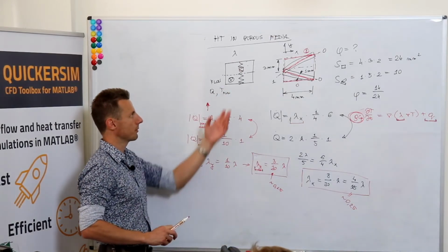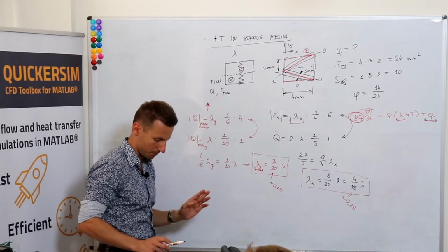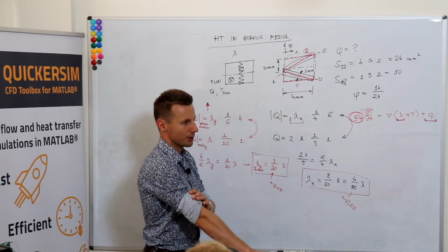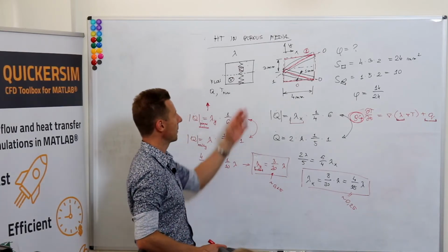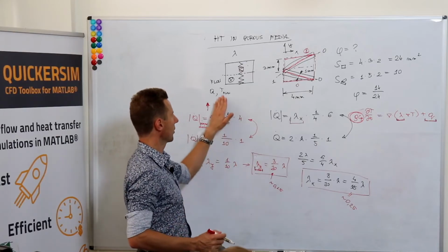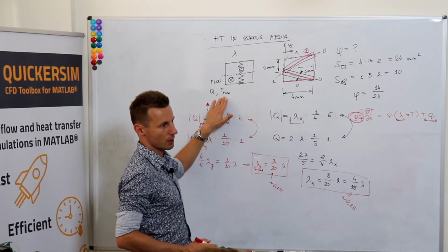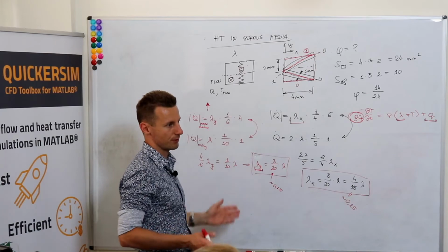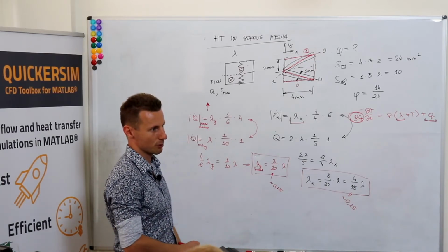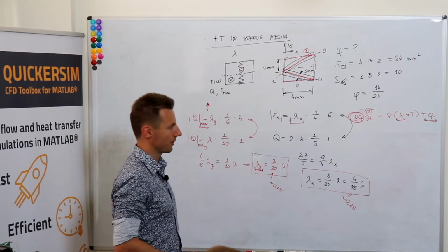If you want to deal with the fluid flow in some different energy balance equation, that's fine. In some cases, you can say maybe this heat exchanger is so short that you simply got flow of air at temperature of 50 degrees centigrade, and nothing changes in the temperature of the air.